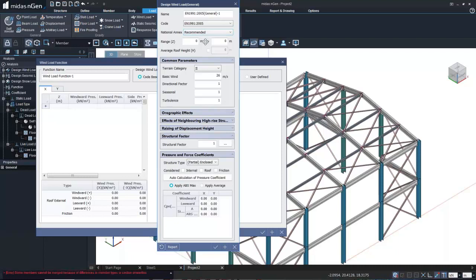Now for applying the lateral loads, usually in many programs, we need to create the story definition. However, over here, we do not need that. We can simply provide the information by ourselves, provided that we have the information. Of course, we will have the information, we are making the model itself. So our height of the structure from ground level is 10 meters, that's what we're providing here. And then further,